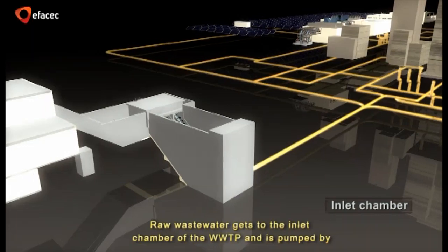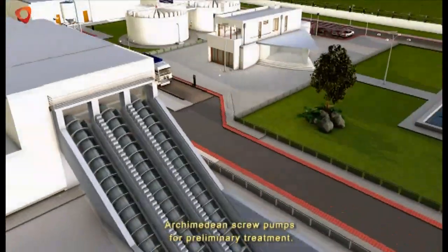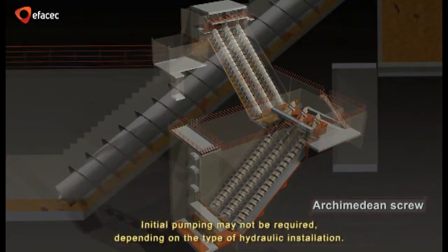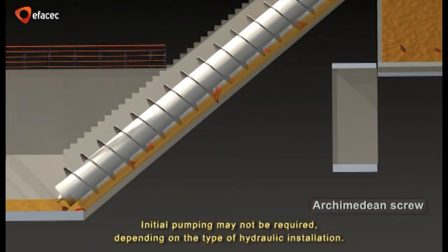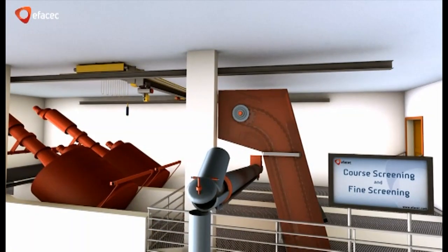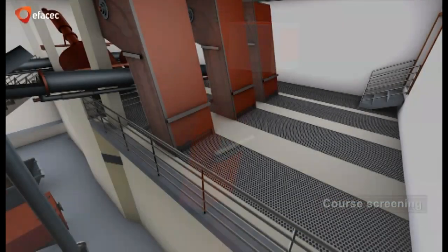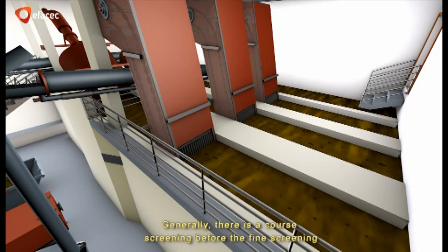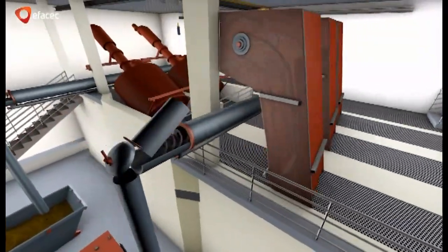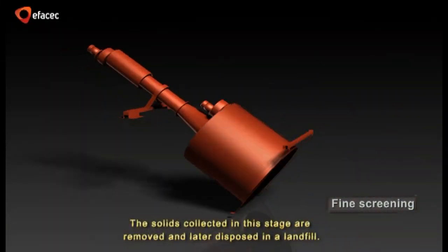Raw wastewater gets to the inlet chamber of the WWTP and is pumped by Archimedean screw pumps for preliminary treatment. Initial pumping may not be required, depending on the type of hydraulic installation. The wastewater is first strained to remove all larger solids. Generally, there is a coarse screening before the fine screening to prevent damage or clogging of the equipment. The solids collected in this stage are removed and later disposed in a landfill.